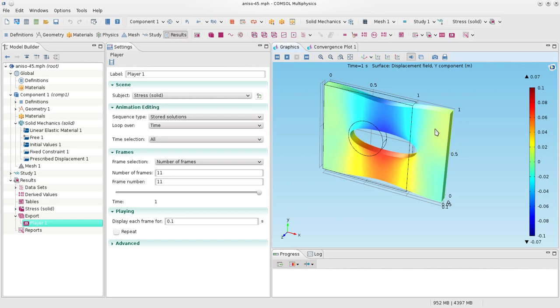Now, notice that the Poisson ratio is equal to 0. So therefore, you don't really expect significant contraction here. But here, you seem to have contraction. Those contractions are not due to the fact that the Poisson ratio is positive. Indeed, it's not. It's due to the fact that there is a hole here which reduces the stiffness of this cross-section, and therefore you seem to have contraction.